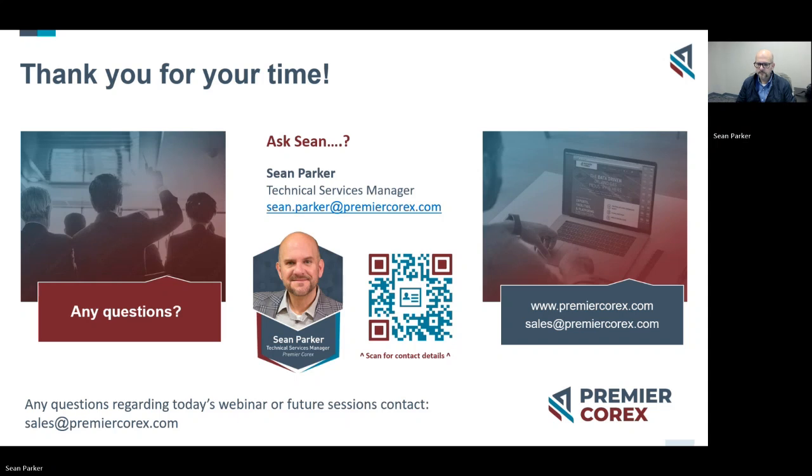Okay, thank you. So we do have more questions now. So Sean, thanks for the presentation. May I ask if you would propose lower or higher mesh for proppants considering shear forces along perfs? So very good question. That's almost in line with do we pump more of a viscosified fluid, or do we increase the number of perforations, albeit at a smaller diameter, in order to maintain limited entry.